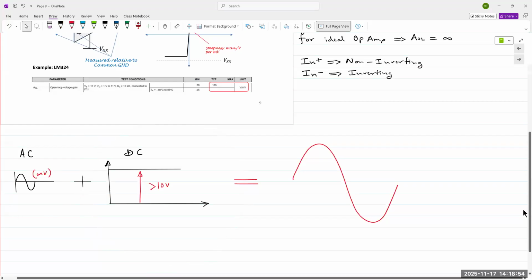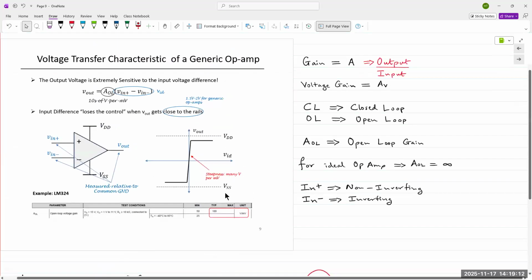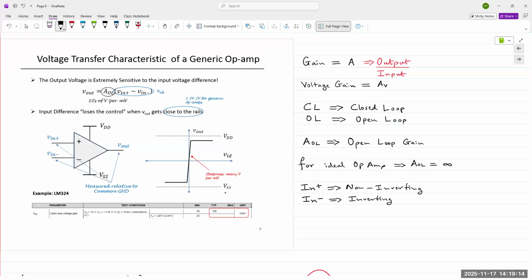Okay. So this AC signal could be in millivolts. The DC biasing voltage could be 5 volts, 10, 15, 20 volts, depending on the system, could be any voltage. And you would obtain a resulting amplified output. Okay, so that amplification energy comes from the DC biasing sources,